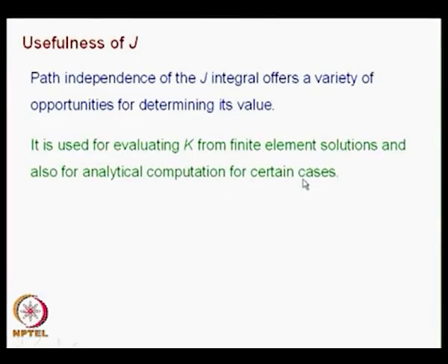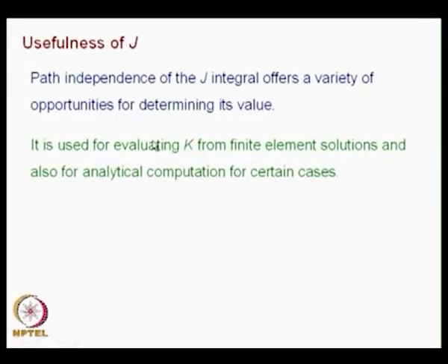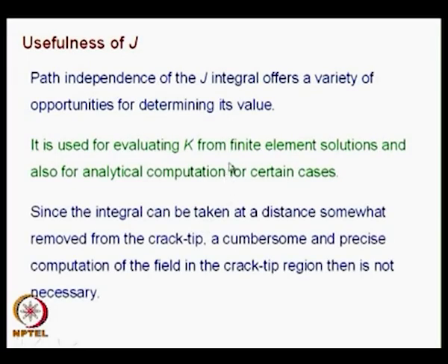What we have done is first evaluate J for a known problem which you had solved in linear elasticity, and we find that whatever expression you finally get for J is the same as G, which is nothing but the energy release rate. And we would see further, because I have the advantage of path independence, what is the use of it in finite element calculations.